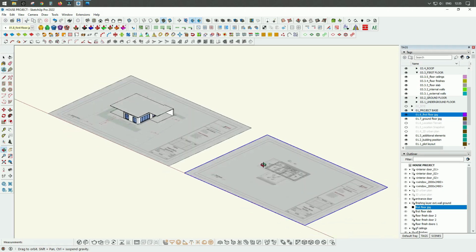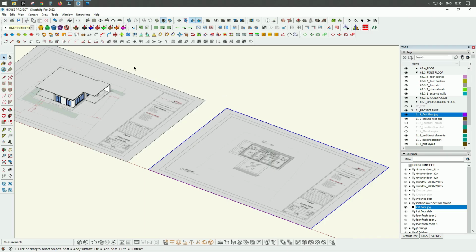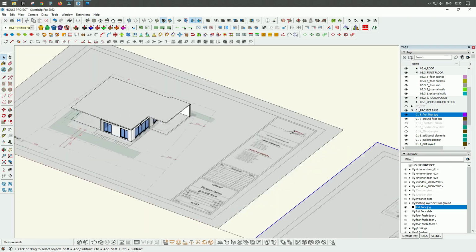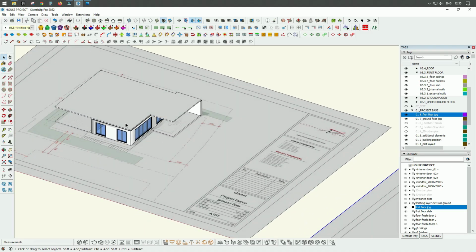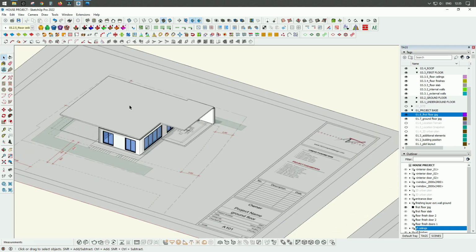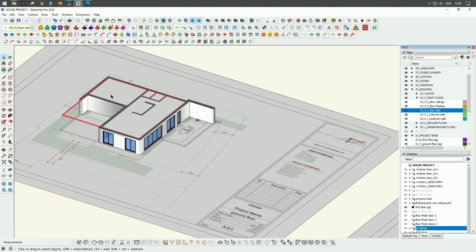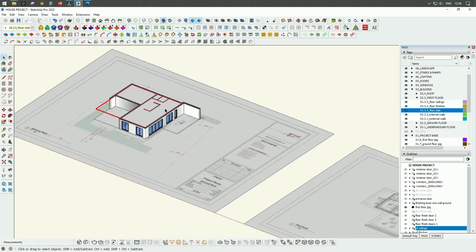So now I'm going to place it exactly where it should be here in our project. At first I will hide for a moment this structural slab in order to see where exactly to place this file, and I will go to our project browser, to the first floor subfolder, and I can hide easily this structural slab.